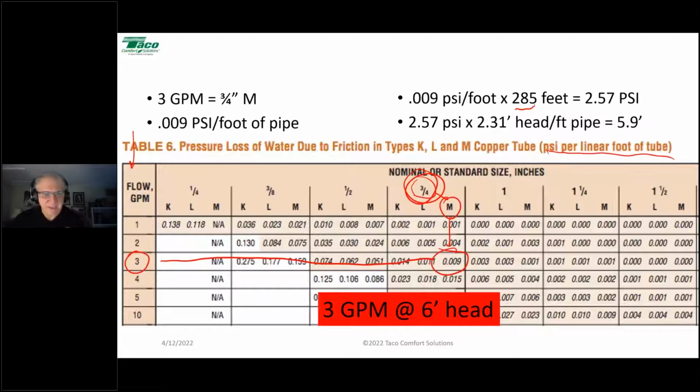Absolutely. All righty. Charles says, don't forget the pressure loss of connected things, valves, coils, etc., in your head loss calcs. Absolutely, that cannot be forgotten, and we're going to bring that up a little bit later, Charles. Right now, we're just doing a 3/4 inch zone of fin tube baseboard that's zoned by circulator. But we're going to get into Cv and things in just a little bit. Very good. Hope you guys are having fun. I know I am. So let's continue.